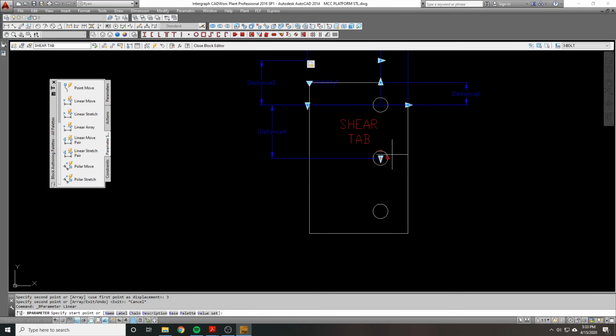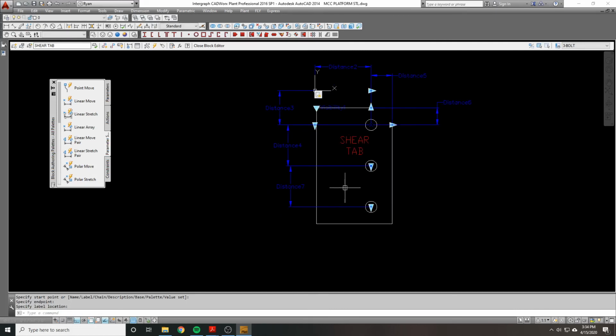So this is kind of some gray area. I have a choice. I can choose to move the entire plate or move just the bolt. I'm going to move the entire plate. So this will control these 2 bolts and the bottom of the plate. This next one from here to here is going to control just this bolt and the bottom of the plate. So I want them to stack on each other because I want the user to be able to control things independently but have the plate follow suit.